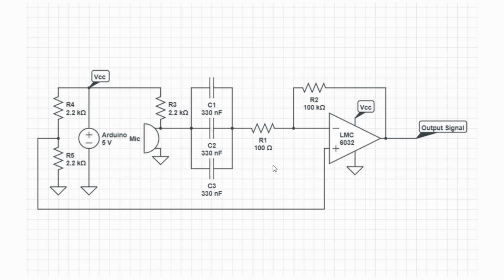This may seem like a high gain considering that the microphone supposedly outputs a signal with an amplitude of 50 millivolts. However, the signal was not that strong. The increased gain generated a more sensitive and precise signal at the cost of some clipping at very high volumes, because the amplifier output is powered by the Arduino 5-volt pin.